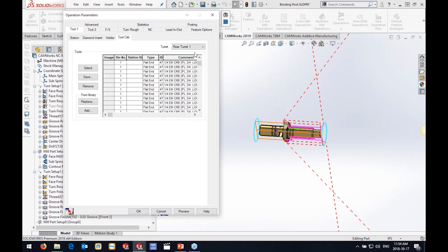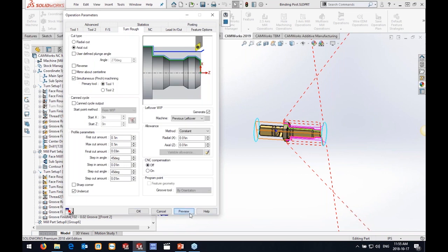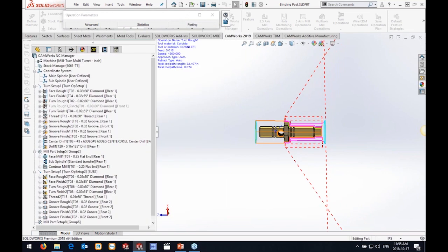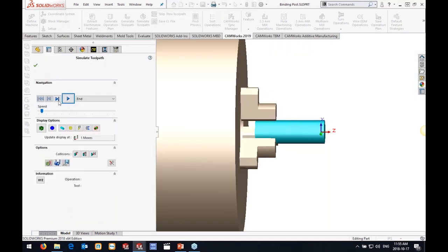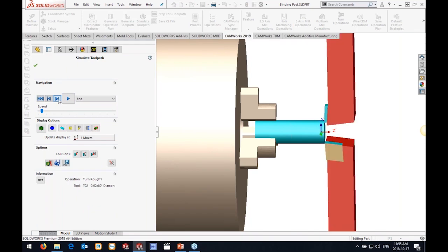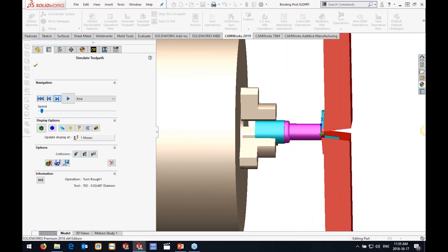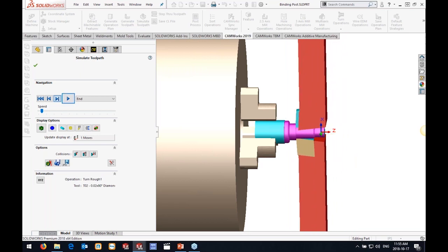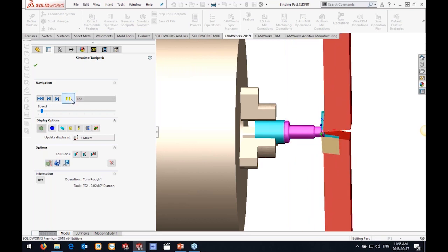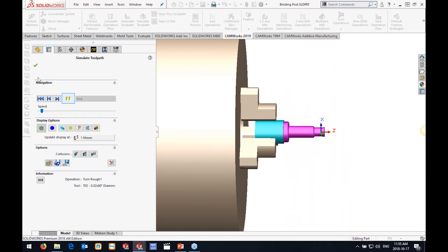So basically coming in together, machining these at the same time, roughing this out. And the benefit of pinch turning is you can crank up the feed rates. Basically, you can double the feed rates, so I've got 2 tools cutting at once rather than just 1 tool going at one time. So you can see now in this case, if I simulate this here, you can see the 2 tools coming in basically at the same time to machine that particular part right down. So we can crank up the feed rate to get these cycle times way down so we can save our cost.